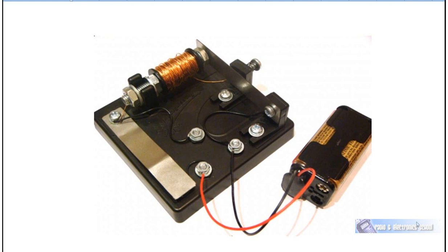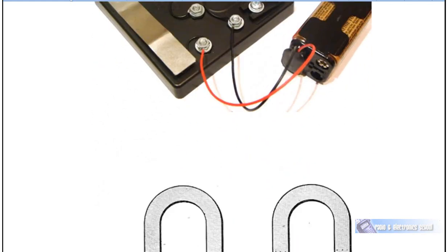If you want to shield a magnetic field from affecting things nearby, and we have coils of wire, inductors we call them in radios, and they have magnetic fields around them, and if those magnetic fields are allowed to go out and stray too far away, they can actually make electrons move in adjacent components in the radio, and that would cause a real problem. So there is a need to be able to block or shield a magnetic field, and what is used generally is soft iron.